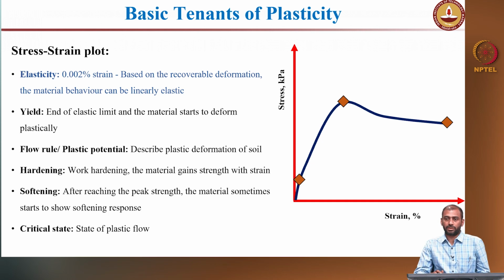Okay, so before going into some more details on the original Cam-clay models, I just wanted to introduce something on the basic tenets of plasticity, right. So till now, the linear elastic model doesn't have any yield or failure, we don't define any yield or failure, and the nonlinear hyperbolic model also doesn't have any yield or failure. So we use a failure criterion for simplicity, but I will discuss in more detail in this particular section the various tenets of plasticity. Then we will go into the original Cam-clay and modified Cam-clay.